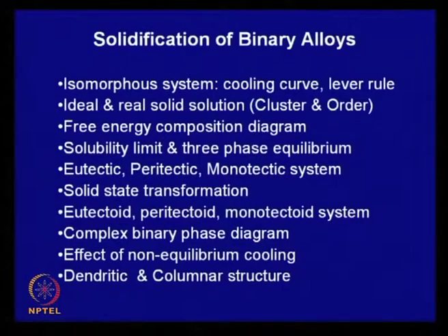Today we begin a new chapter, and this chapter is on solidification of binary alloys. Now, the topics which we will be covering are listed here. We will first start with the isomorphous system. We will define what it is and what the cooling curve is. We will also derive an expression which helps us find out phase percentage, which is known as the lever rule.